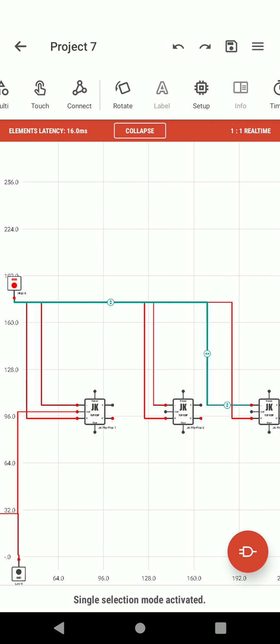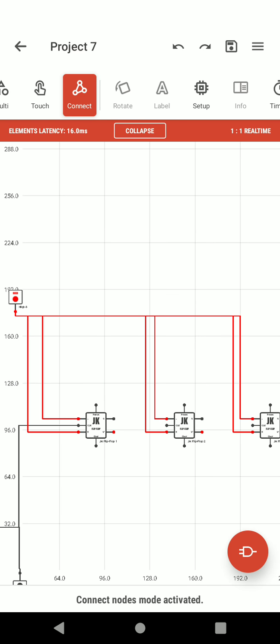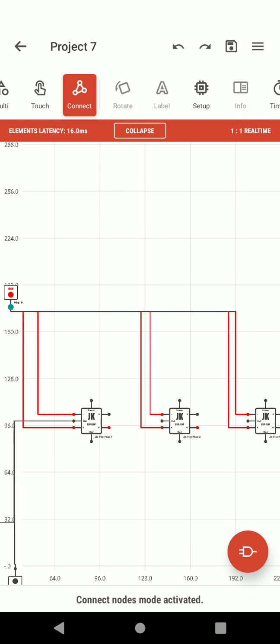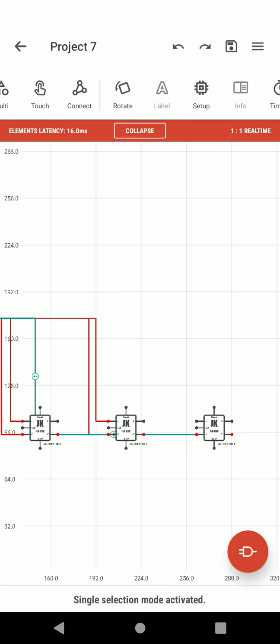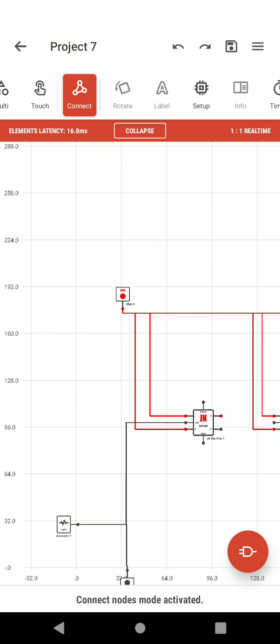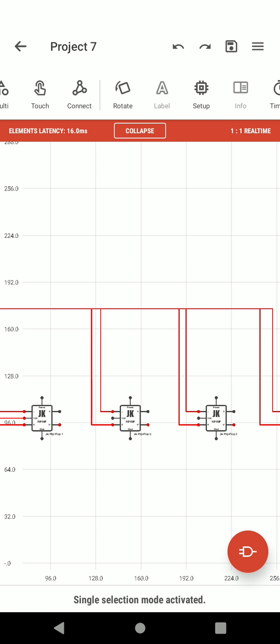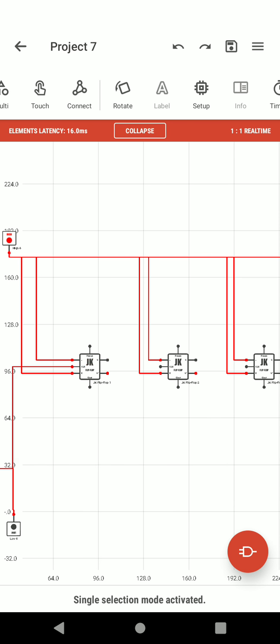So just slide this one, and next again connect high to K of the fourth flip-flop. Just move it. Just connect high to J of the last flip-flop. Just connect them. So here's the thing: only the first flip-flop is blinking, because we have given the clock to it.